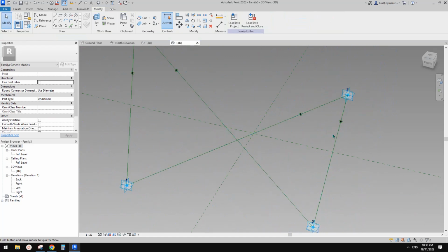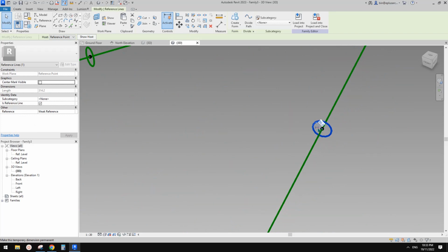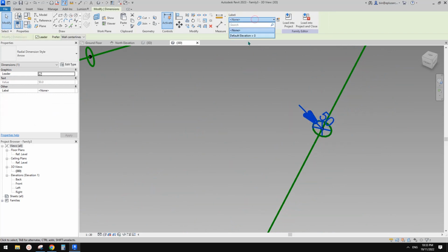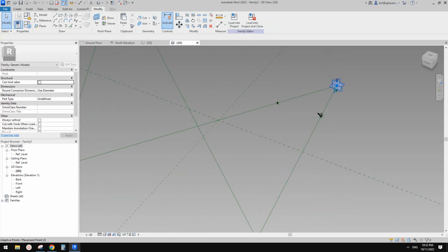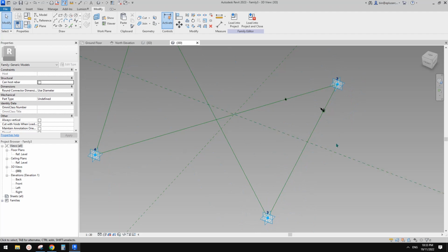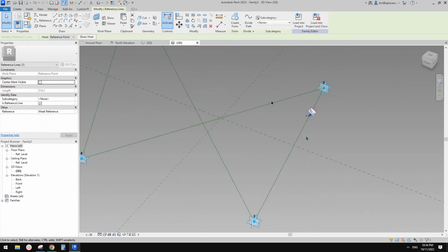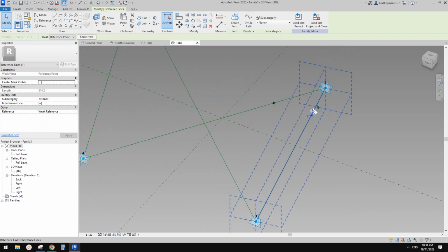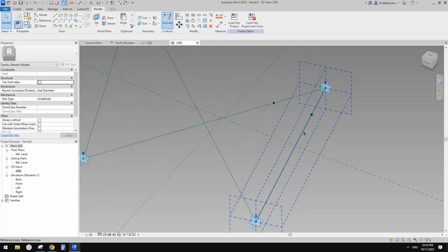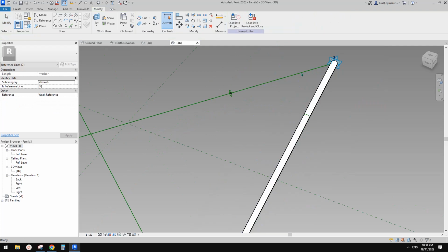And also remember, if you want to control them in the project, if you add dimension and create parameter, make sure for each reference line you need 2 profiles. Okay, so you need 2, but for this exercise I'm not going to control the size, so I'll just use one profile, and just make sure, so tab, select only this path and this profile, create a form.